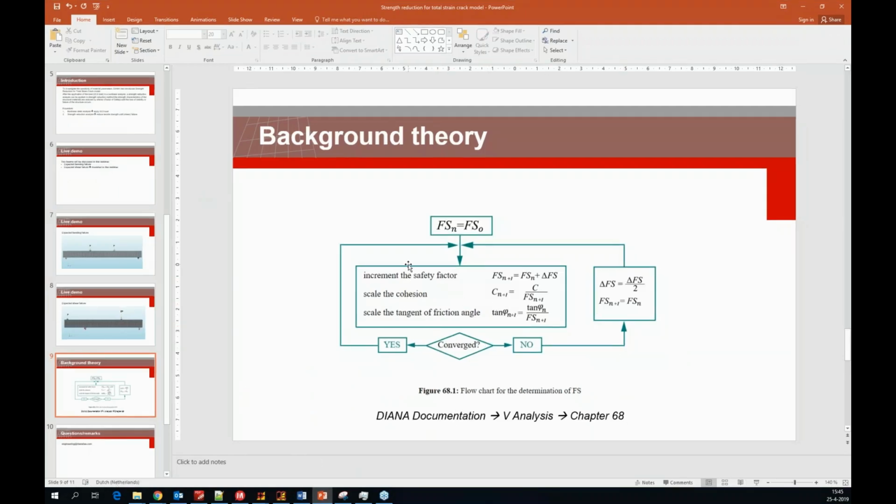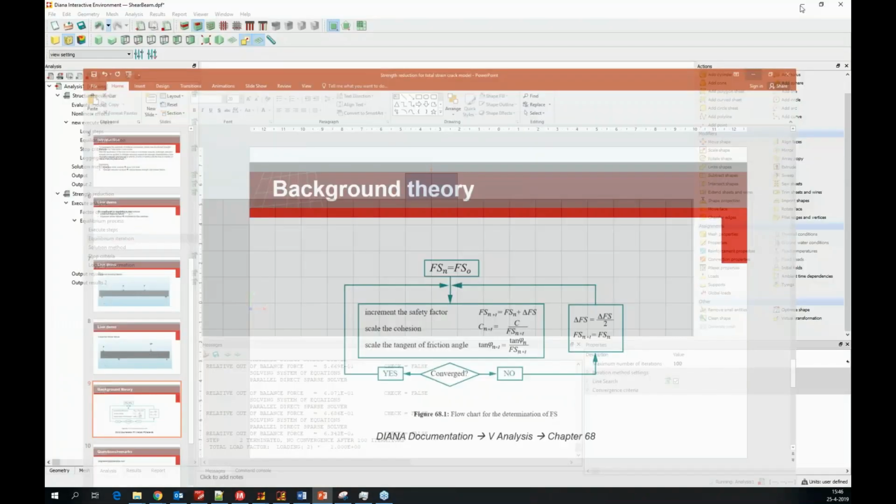This is usually how it works in general. So you saw that for my convergence options, I used continue even when there's no convergence. Then this flowchart doesn't work anymore. So you have to say terminate, and then the factor of safety increment will be divided by 2 if there's no convergence. If you use continue, that is allowed, of course. You can just use continue.